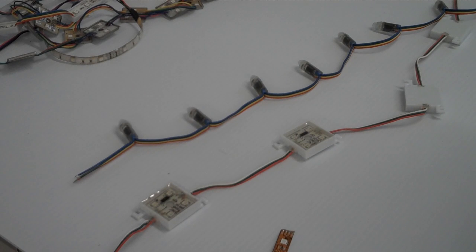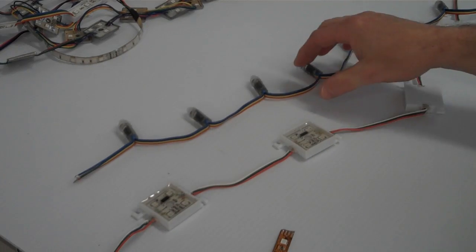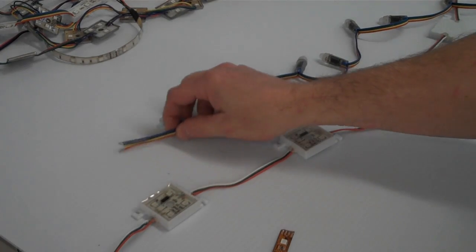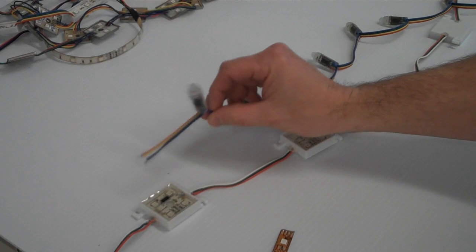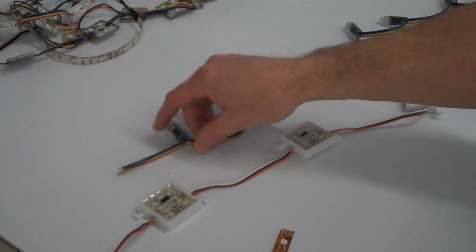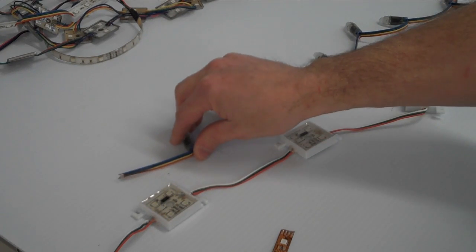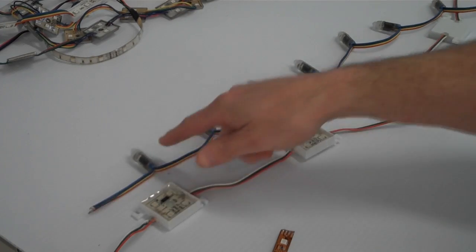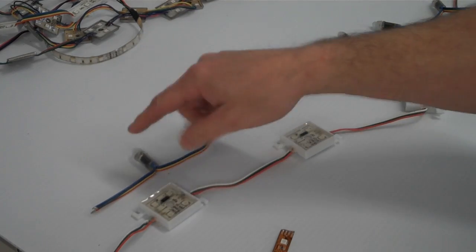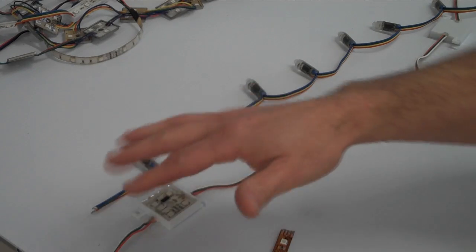Now, controllers also have built-in hardware-based macros. Some of these are done to overcome limitations in software, which exists today in sequencing software. Some of them just provide additional functionality. One of those is phantom channels. So, for example, let's say that you really just want to treat your pixels as if they are one long string of basic RGB devices. So you really don't care about controlling them individually. You want all of them to turn red, all of them to turn green, or all of them to turn blue.